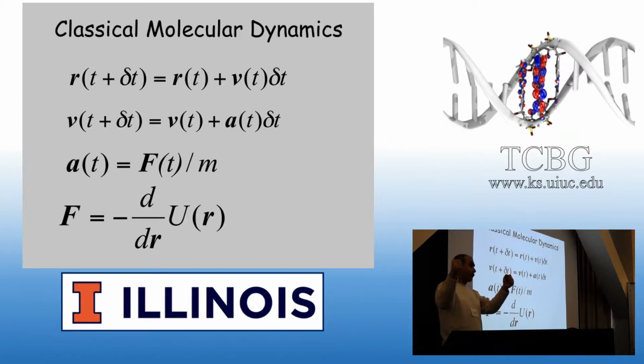It's going to be a huge force going back because it has displaced too far unnaturally. That's going to pull it back very strongly, with very high force. And then you're giving it a long time step, it might even go to the other side. That's going to kill your simulation because it's going to get unstable. Things are going to diverge. That's a technical aspect of the issue. We can't do it. But if you even think about this, you have this periodic motion going up and down.